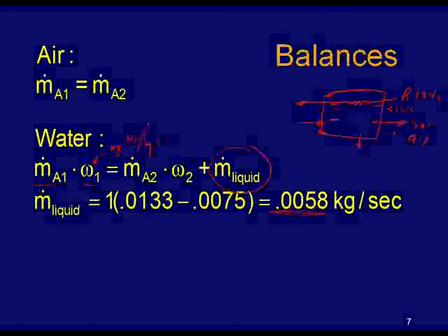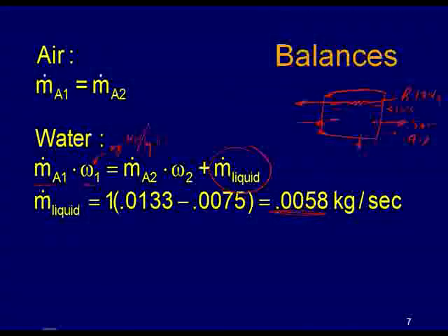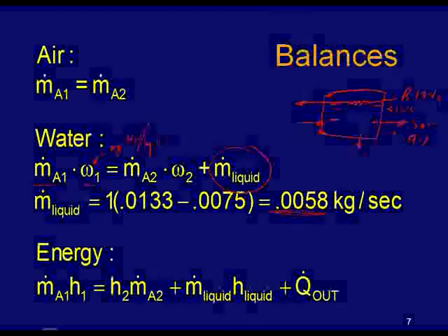So we make it maybe 5 degrees C or 0 degrees C so that we can draw that heat out of the air. That's an important concept, that driving force, or minimum delta T for heat transfer.